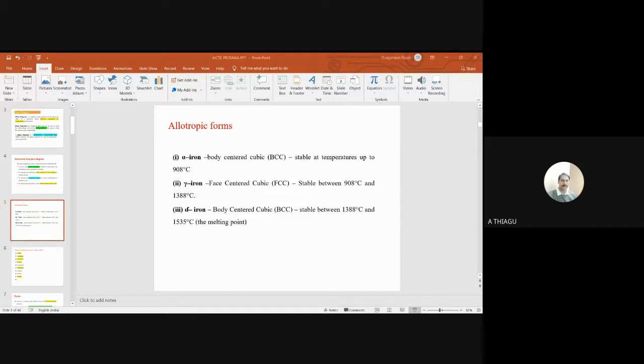Now white cast iron: you can see the appearance of the structure in the form of white. It has unique properties: hardness and very good abrasion resistance, but a very brittle nature. This is the drawback of white cast iron. It is a combination of many carbons, or carbides, that are present. You can see the black color, where more carbides are involved.